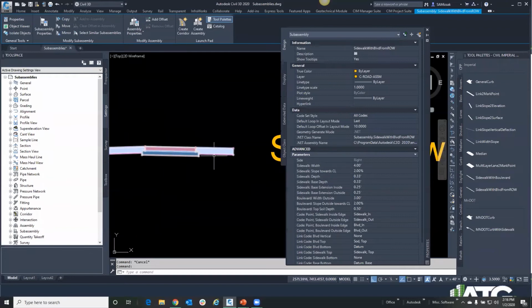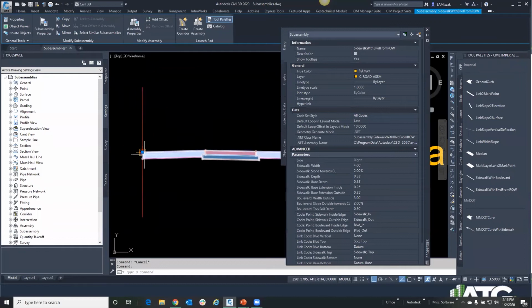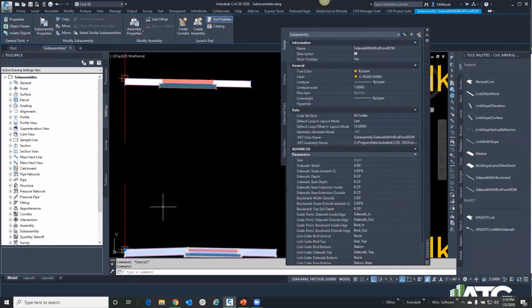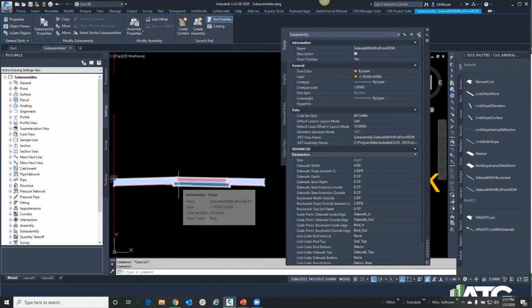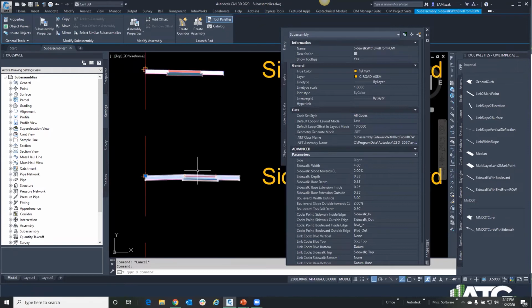Because I need, maybe this is at the right-of-way line, or maybe this is at top of ditch, and I need all this to be working my way back. But when I get to my top back of curb, all the slope needs to go in here instead of up in here. But other than that, the extensions are the same, the depths are the same, everything else is the same. Targeting, the 3 spots, still the same.